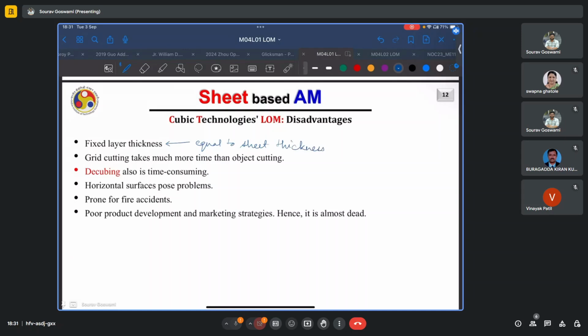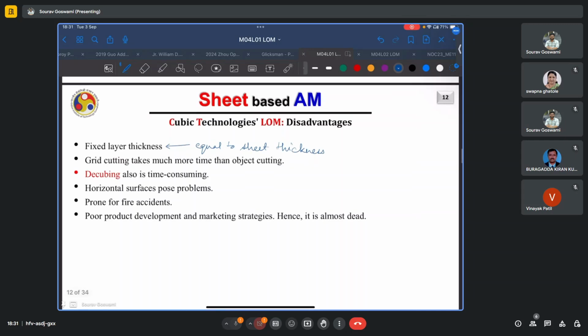And thus, if you have a build which is of a regular geometric shape, does not have regions with high curvature, this will still be okay. However, if you have a geometry which would have benefited from adaptive slicing, where you use thicker slices for linear or rectilinear regions and thinner slices for regions with high curvature, you lose out on such advantages and the final build quality and accuracy of your build is affected.